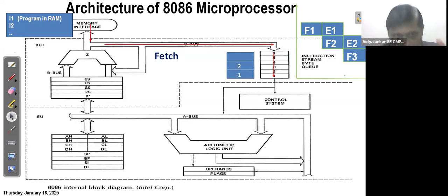See, when you fetch, instead of looking in 1 MB, now you have to only look into 64 KB. Why? Because what you fetch is an instruction. What is an instruction? It's a part of the program. And where is the program? Program is in the code segment. That means your processor will only focus on the code segment.